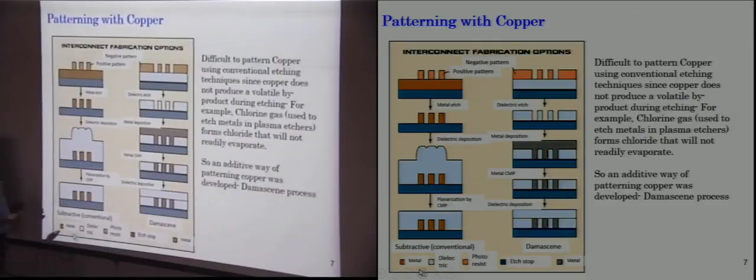If you are doing wet etching, in this case, let's say you start with a positive pattern on top of the photoresist. Let's say we are etching aluminum. Okay. The photoresist blocks the etchant from attacking the aluminum below it, and then when you remove the photoresist, the pattern on the photoresist has been transferred onto aluminum. Okay. And then you can deposit and planarize and things like that. But basically, if you are etching aluminum over here, when we are utilizing an acid to etch aluminum, that acid is converting aluminum into something which is soluble and washes it off, if you are using liquid etching.